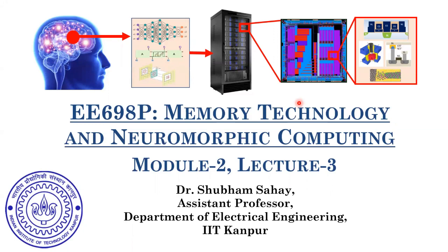In the last lecture, we saw the structure of the SRAM cell, which comprises a bistable element with two access transistors by which you can read or manipulate the data stored on that bistable element. We also saw how we can read the data. Then we saw the constraints on the size of the access transistor and the pull down transistor of the inverters in that bistable element, which should ensure a non-destructive read.